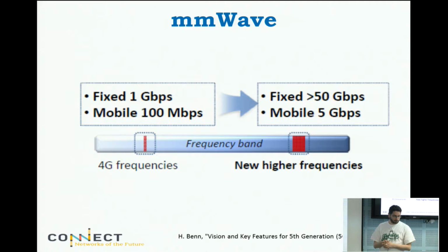Okay. And then there are RF complications, and what I know of millimeter wave bands is that they are also very susceptible to line of sight blockage. They are not at all exploiting the multipath phenomenon as at lower frequencies. You really have to see the user, I mean electromagnetically see the user, and transmit to the user. So you cannot exploit reflections, right? Because anything else will be too weak by the time it reaches the receiver.